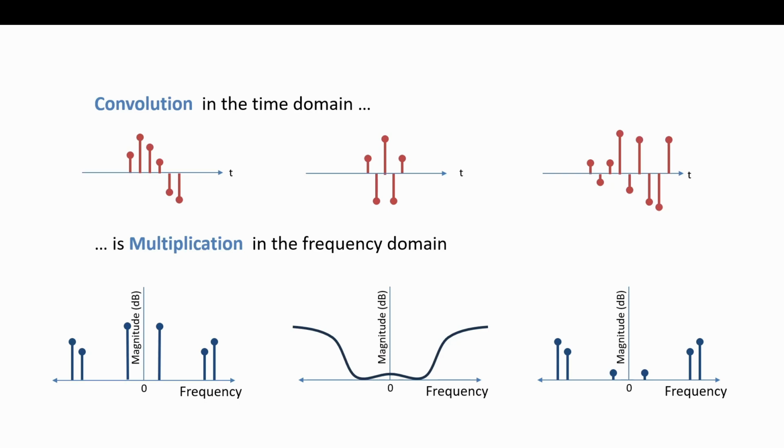Is that a real waveform in time or a complex waveform in time? Let's just see if anybody knows this stuff. It's real, right? So if it's real in time, it's complex conjugate symmetric in frequency. We think it's real. I'm not showing you the phase, so maybe I'm tricking you, but that's a nice takeaway there. If it's symmetric, then it's real in time.